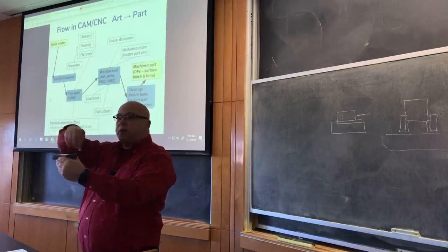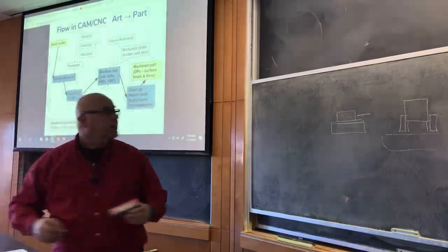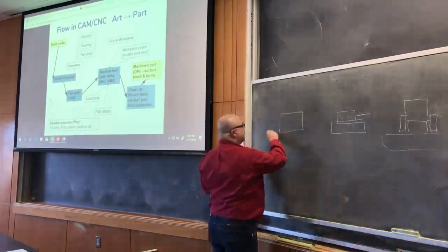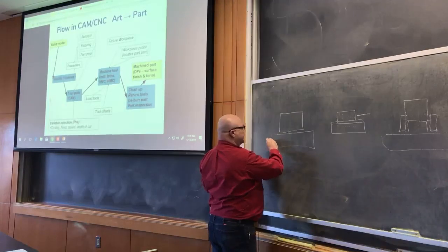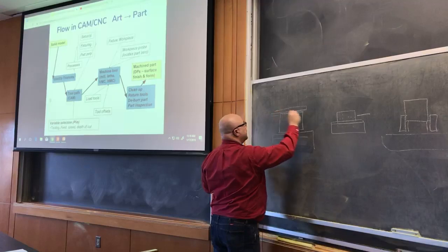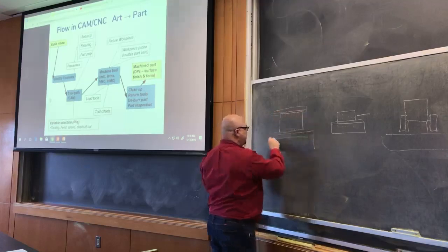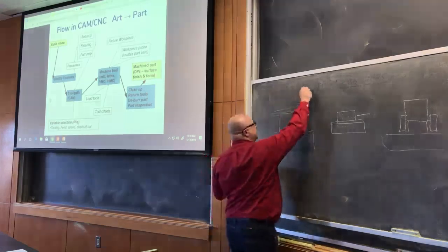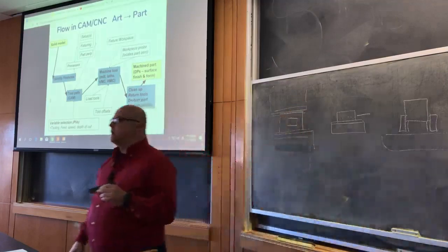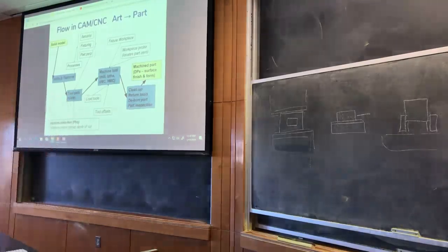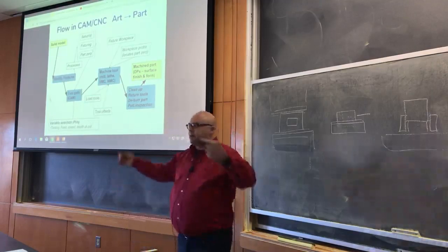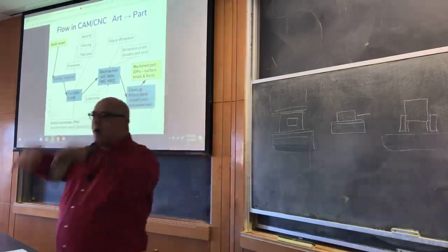I could go around the outside; we call that a contouring operation. If we look at the top-down view here, with my parallels in there holding the part up and the vise going out like that, I could make a feature that goes through the part right there. What do we call that feature? Does it have to go through the part to be called a pocket? No. It could be a blind pocket, which doesn't go through the part. A through pocket goes through the part.